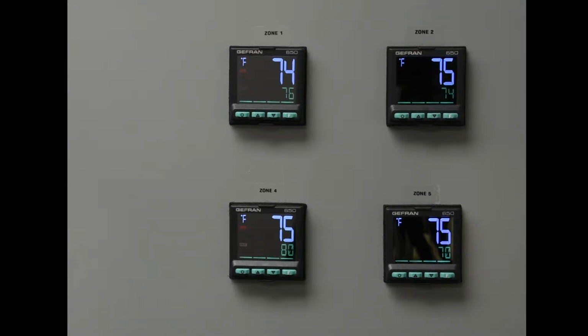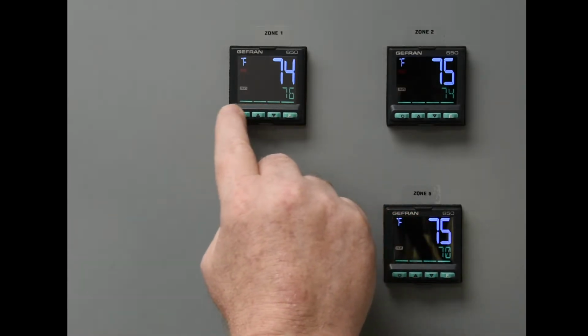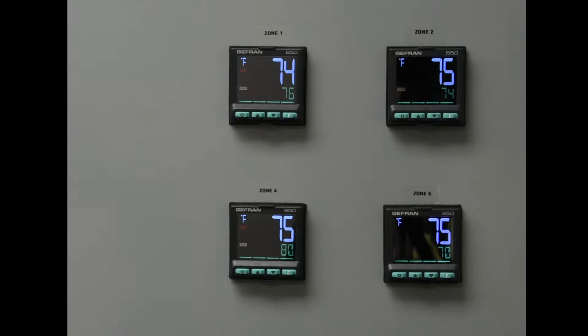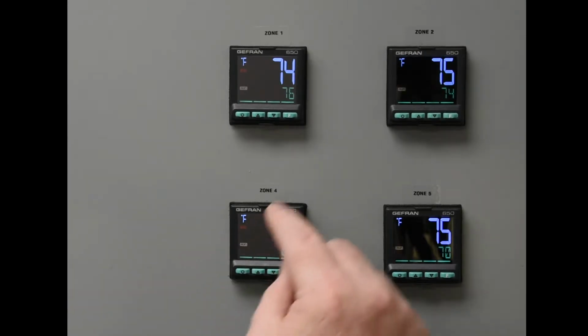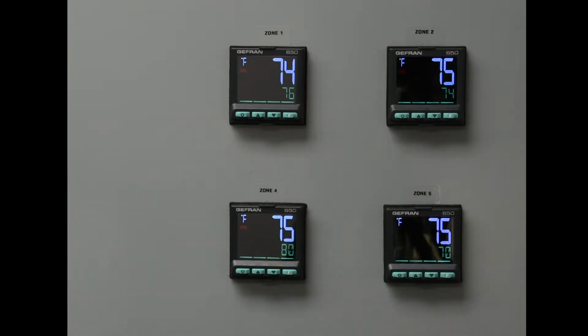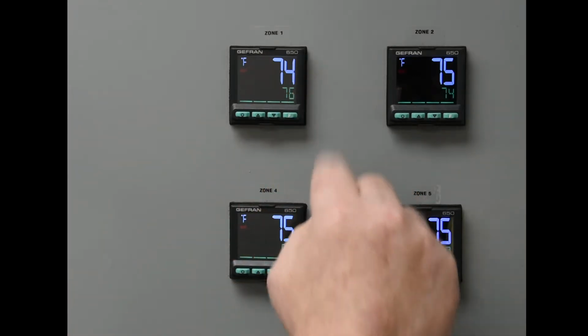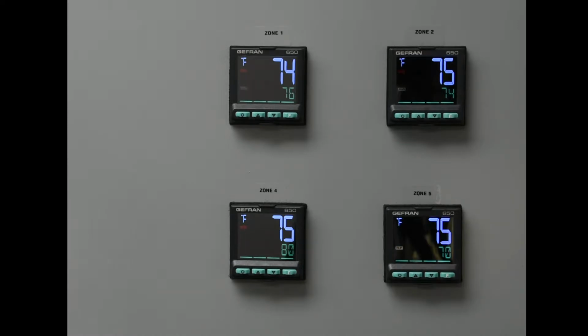Above that will be the 4 bars that will display which keys have been pressed and what is active. The smaller numbers displayed in green display the SV, which can be the set point value, which would be the number, the temperature which is being programmed. The large numbers will show the PV, process value, or process variable, otherwise known as the current temperature.